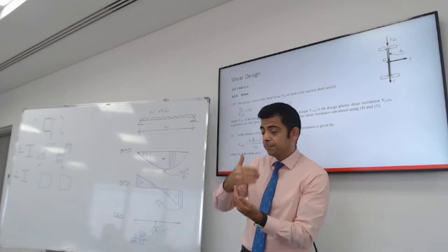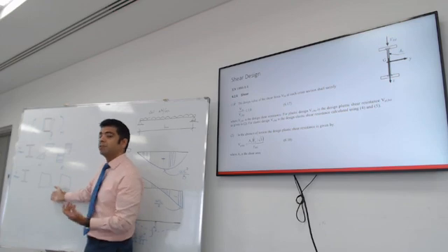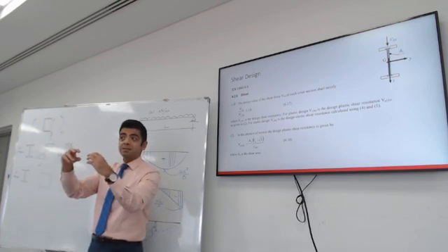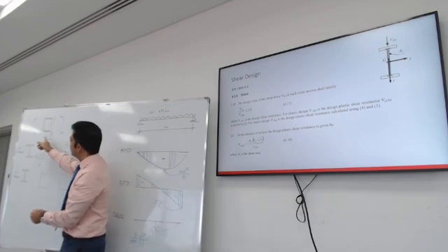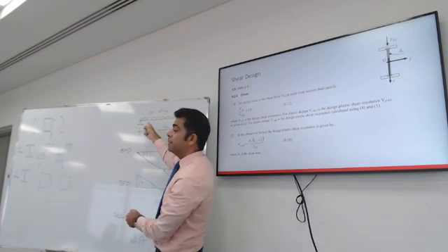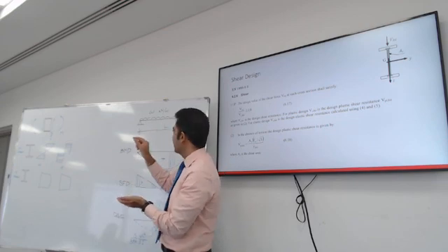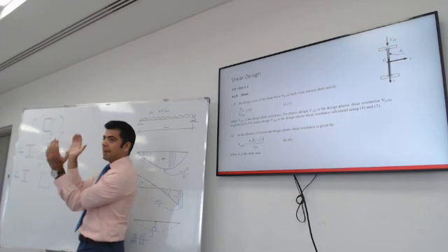For shear, this is the shear stress distribution over the section. I need you to know what bending does to the beam and what shear does to the beam. This is a small section of this beam. It is an IPE section with a top and bottom flange, and it looks like an I. If you take a chunk of it, the bending moment is trying to bend it.